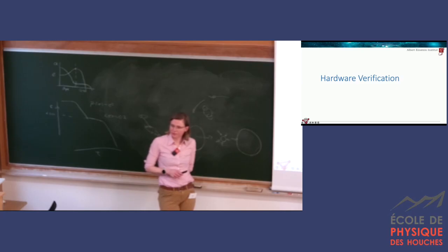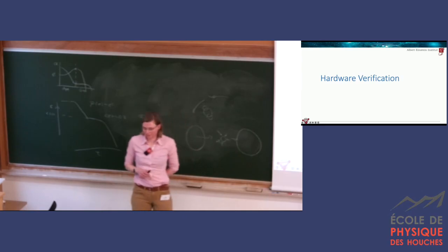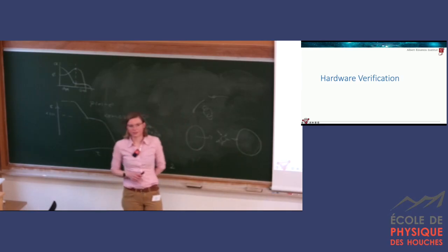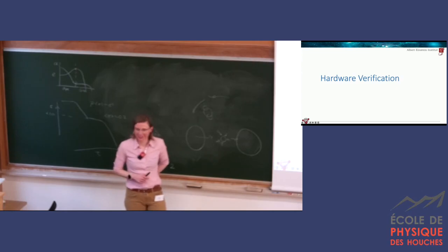And Ada said it, you have two ways to go. From your science requirement, you say, if I want to measure this, it means that on the topmost level I have to have this noise at most. And then you budget, you assign the noise to the next level and so on. So that's what Ada called allocation. Yes. And you can go the other way around: I have experiments, I test my stuff. This is my best estimate of what the noise level of this block is. Then I sum it up, I go up, and hopefully in the end you should be below the allocation.